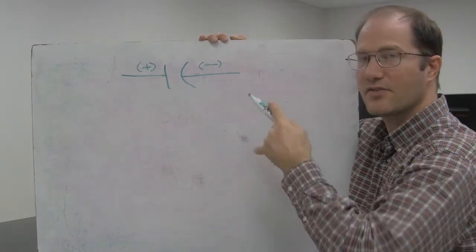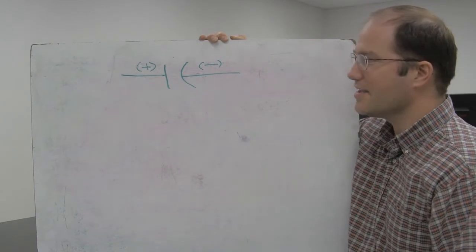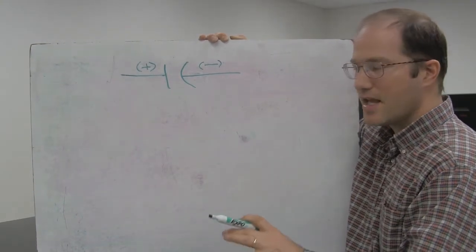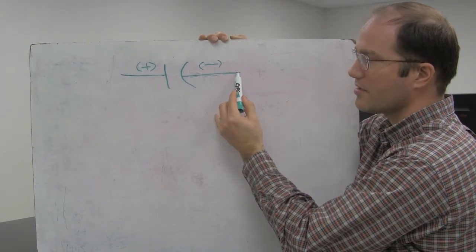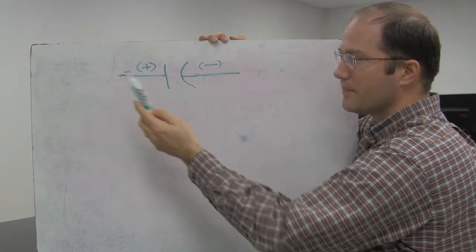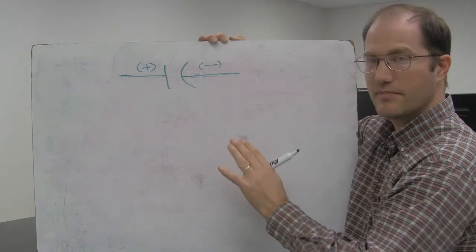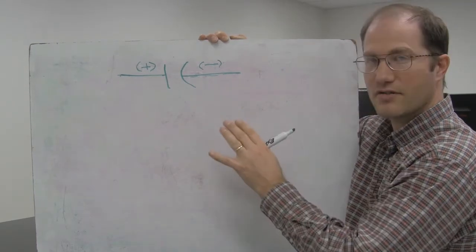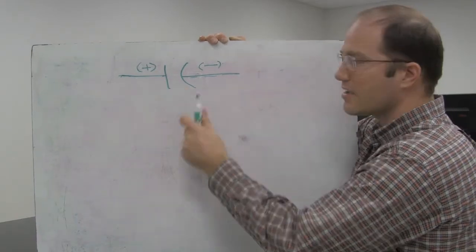Because if you get a capacitor turned around the wrong way, it becomes a tiny firecracker. So we want to be careful with the setup in today's lab. If you're not sure you have your capacitor turned correctly, with this side facing the negative terminal of the battery and this side connected to the positive terminal of the battery, either side through the resistor, then bad things will happen. So check with your lab instructor to make sure before you actually connect it to the battery.